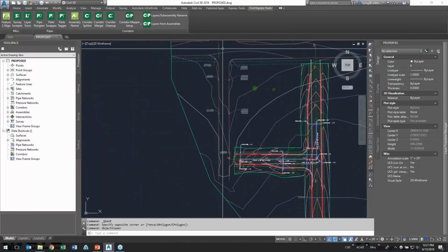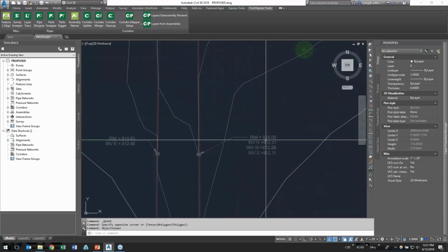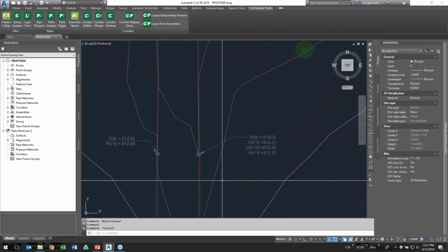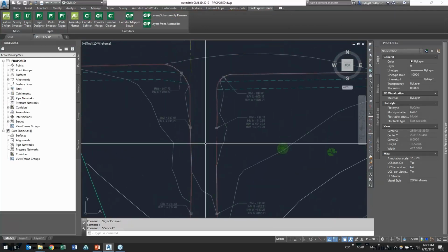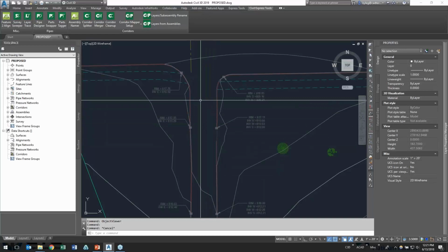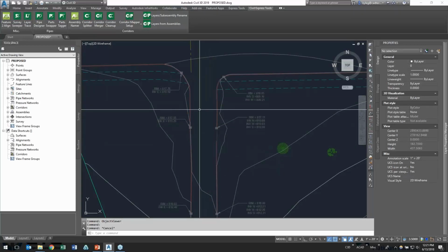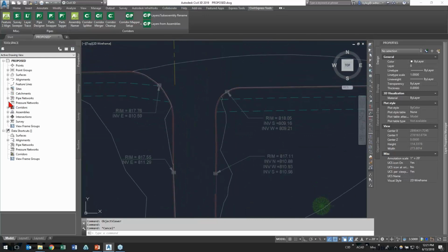And then on the west side of our site, we've got this other small access road with our surveyed design information. Now, this could come in a few different forms, whether it's a full-on Civil 3D survey point or COGO point, or if it is just multi-liners and blocks, which is what is XREF'd in this case.